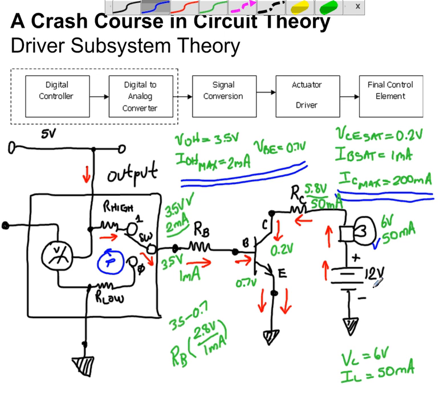the power supply that you intend to use as an energy source for your load, the specifications for the transistor that you select as a driver for your load. Be sure that the current requirements or the maximum current for the transistor is large enough to handle the current that's required for your load.